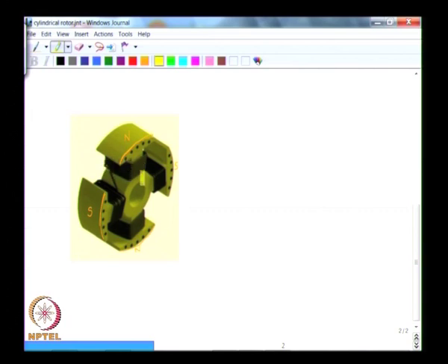You see that coils have been wound around this, and this winding is then connected in series with coils that are wound around this pole, in series with coils that are wound here and then wound here. So this then provides the way to excite this field system.